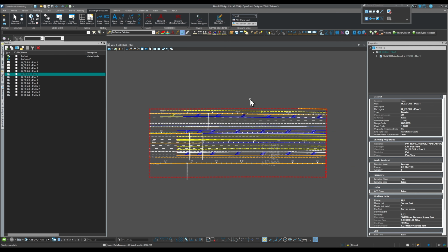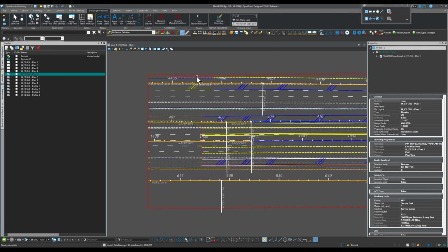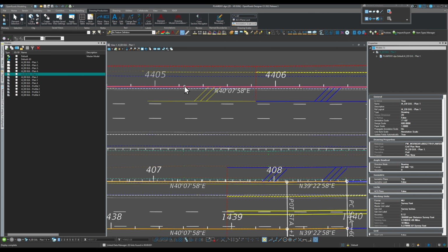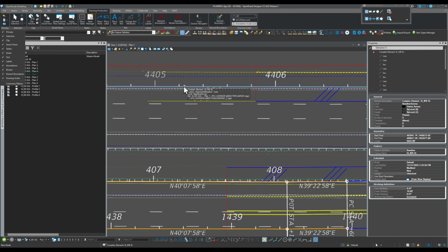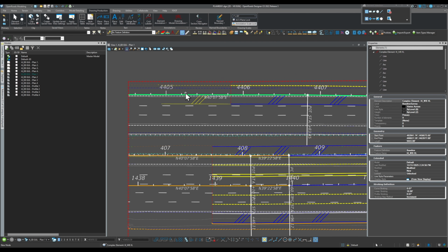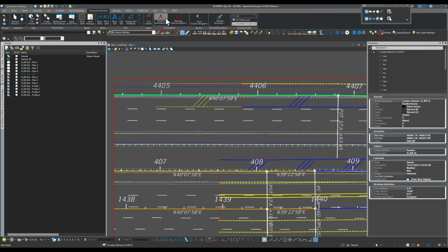By default in ORD, or at least in the Florida workspace, whenever you create a drawing model, ORD will go look at these elements and look at their feature definition. If you remember from the beginning, I said ORD cares about feature definition. In this workspace, and I'm saying this workspace because I've seen some other workspaces, they do this automatically; you have to annotate the element manually. But in Florida, for some reason, they coded that within the seed of their drawing model. It will go find the feature definition and automatically annotate them.